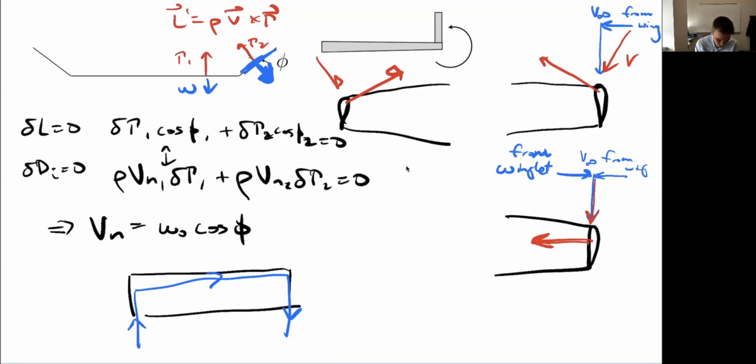So if we look here again in our side view, let's imagine this case again, right? The winglet, it induces a downwash on itself. So the circulation, remember here, is going left to right. So I rotate that, now it's going vertical. So I've got kind of this circulation. Here's my winglet in this side view, and it's generating a downwash on itself. So there's this horseshoe vortex.